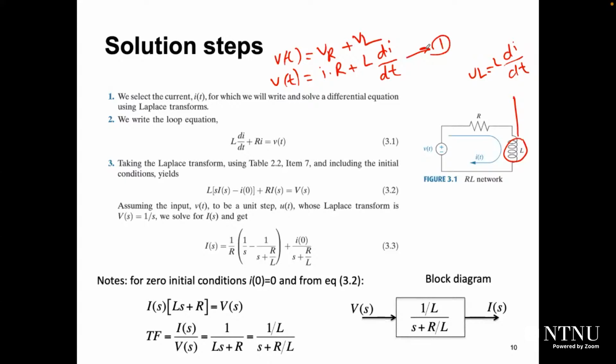After that, if you want to get the transfer function from this equation, remember the definition of the transfer function: we assume zero initial condition. So just apply Laplace transform to this equation. So it will be V of s equal R plus Ls, whole multiplied by I of s, correct? Because we are assuming zero initial condition.